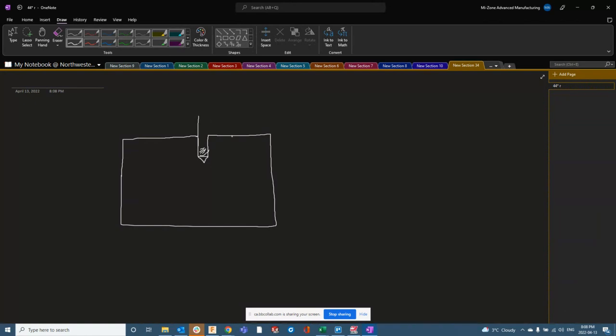So whenever you're doing blind holes, if I say to do tap to 1 inch deep, right? Then what I want to see, and actually this will be on the test, so if you don't understand this, please reach out to me. So if your tap depth is 1 inch, right, meaning that we want 1 inch of thread, we're going to add on, remember that, so our drill, instead of going down to 1 inch like we would here, it's actually going to go just a bit further, like this.